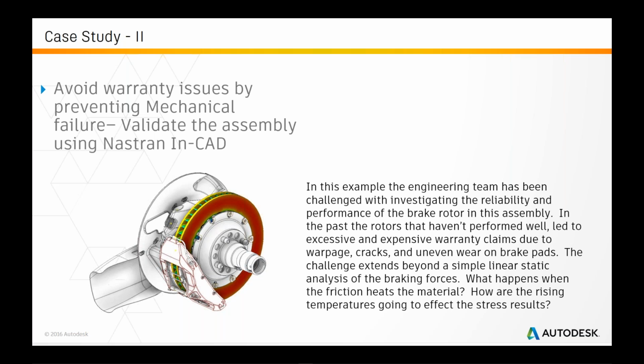What is happening with this particular rotor is that it's leading to expensive warranty claims due to warpage, cracks, and uneven wear of the brake pads. The challenge extends beyond simple linear static analysis for the braking force. Here we are going to simulate a couple of scenarios where heat is pushed into this rotor because of friction, and then simulate how the deformation in the rotor happens, and whether we can make changes in this rotor so that the design is made safer.